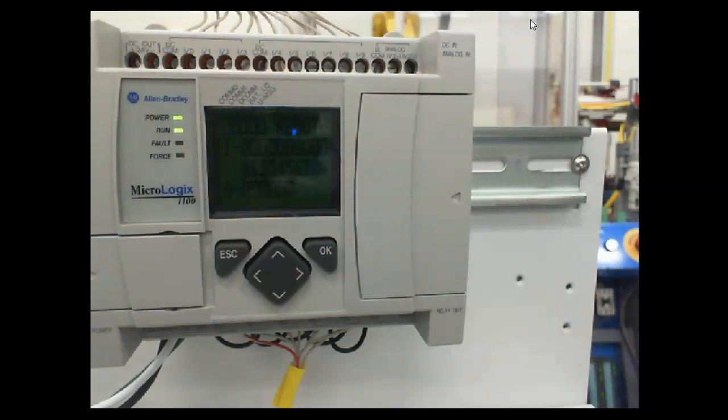So below 50 volts, you don't have to wear near as much PPE as you do as soon as you get above 50 volts. Then you've got to start adding PPE, and the higher voltage and energy you have available, pretty soon you'll be wearing bomb suits to work on this kind of stuff. So what has happened over time is PLCs basically operate on 24 volts DC, which means on the PLC side we can operate on very little PPE. But as soon as I get up to 50 volts, then we've got problems.